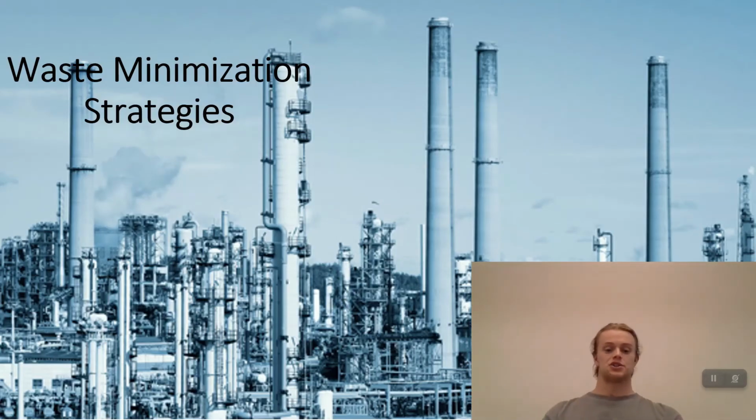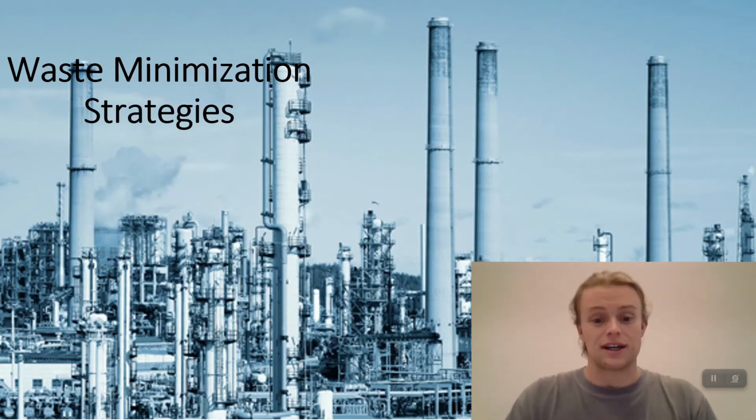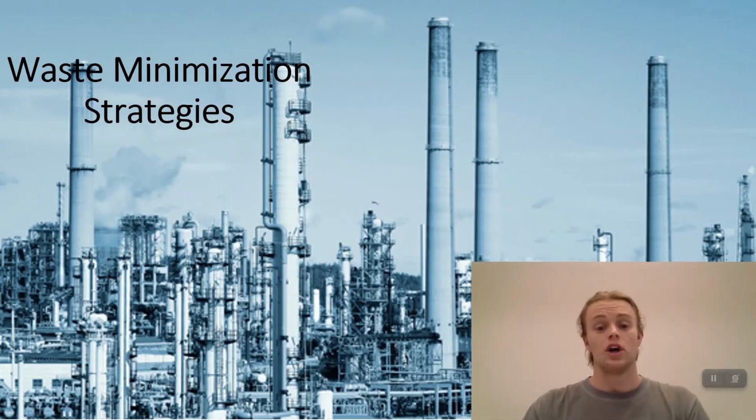Waste minimisation strategies can include vast infrastructural investments, revolutionary methods, or simple operational and practice improvements. The automation of the industry has seen a reduction of over 80% in oil spills, which had previously been attributed to human factors. The automation of VOC-run UK refineries presents a very good example of the role of autonomy in industry, with the autonomous pH adjustment of over 20 megalitres of wastewater per day to suit the fluctuating 6-hourly tide, reducing the concentration of discharge and the impact of the effluent on the environment.